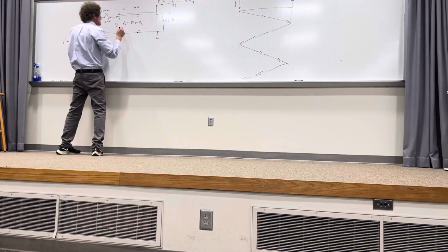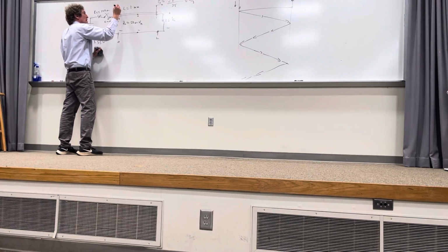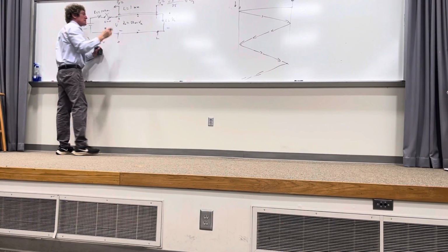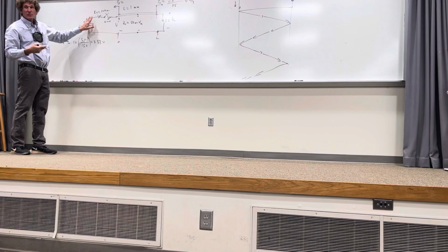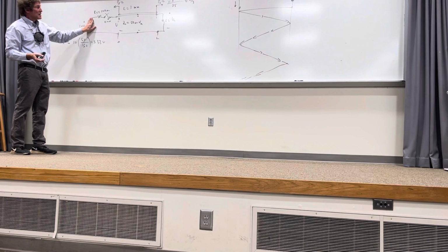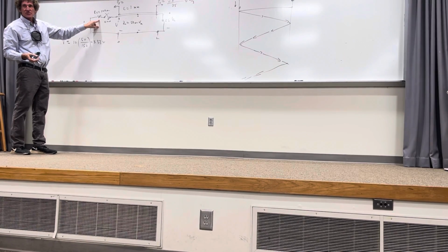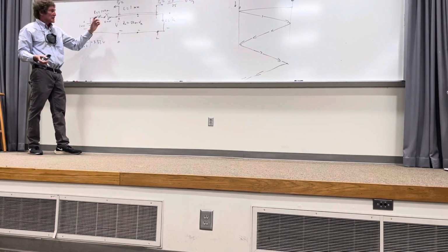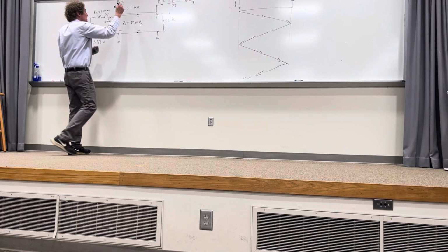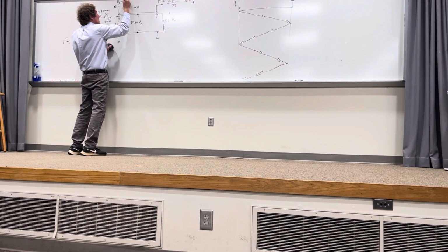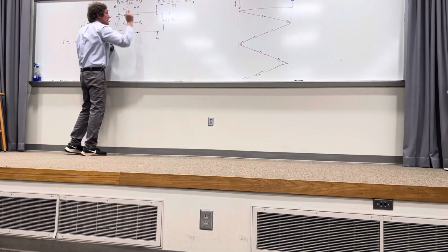Then we have to get the reflection coefficient here, and that's the reflection coefficient at the source. And the way you do this is, again, you use the Thevenin equivalent circuit of this thing, or you look for the Thevenin resistance. That means you short this voltage source out. Do y'all follow me? You just take this as your effective load resistor you're going into, because the pulse is reflecting this way. So it would be 100 minus 50, or 50 over the sum of the two, or over 150. So here we have 100 minus 50, or 50 over 150, or this is plus 1/3. Agreed?